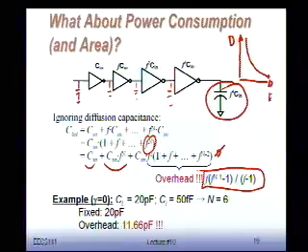Okay? So I pay for that in terms of power, because you have to multiply this CL times VDD squared. Every time, this one is going to go down, this one is going to go up, this one is going to go down, this one is going to go up. So extra power dissipation. Okay? It's actually, the numbers can be quite high. For instance, if I want to drive a capacitor of 20 picofarad, and I assume, let's say, that the input capacitance is 50 femtofarad. So the ratio between those is approximately, we can compute the optimal n using our factor 4 scaling factor, right?